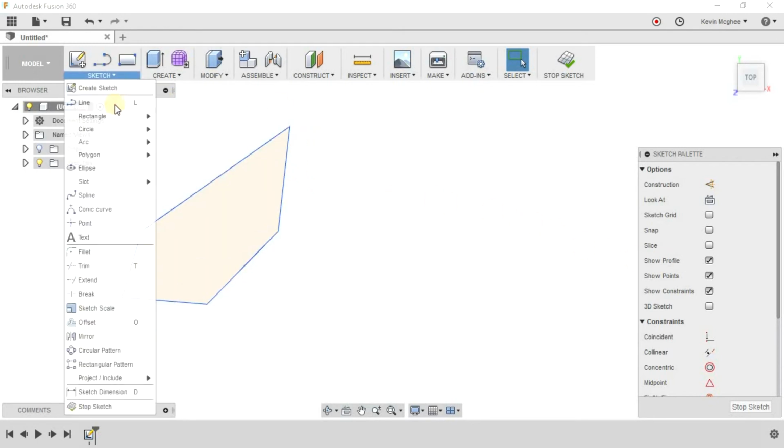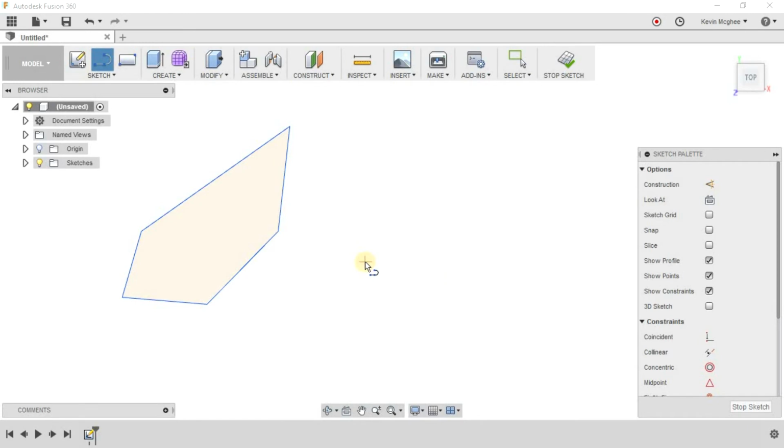So the other thing we're going to do is we can enter in dimensions. So I can enter 3 inches, and I can tab over, and now there's a little lock symbol next to the 3 inches. So I cannot change the length of that line. The only thing I can change is the angle. What I can do though is type in an angle, and it works. Negatives won't work. You have to know your degrees. So you'll have to understand what that needs to be.